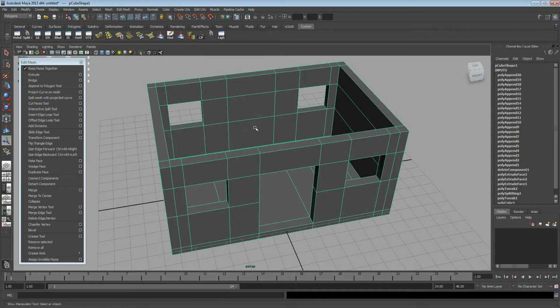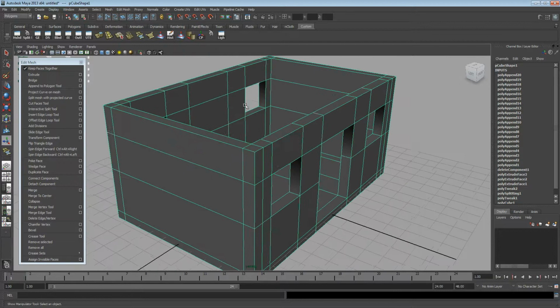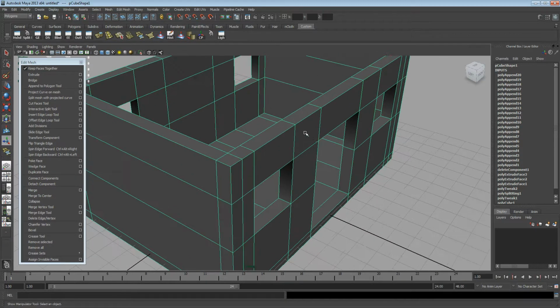The first thing, especially after you have created the faces that are needed to fill up the holes, the very first thing that you would want to do is check the normals of your objects. And what are normals? You can imagine this, because a plane by itself is unlike a plane in the real world, like a piece of paper. The paper is double-sided, but the plane itself is not.